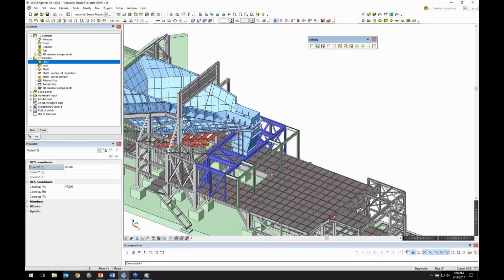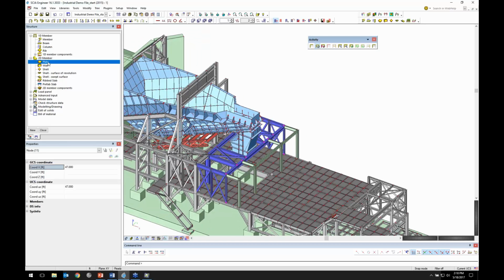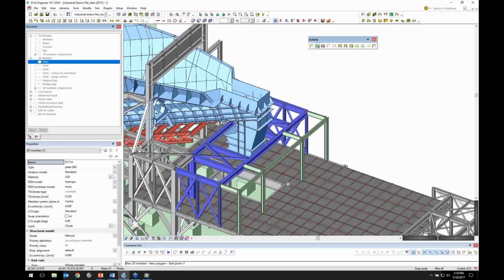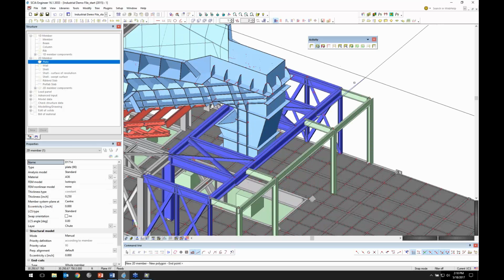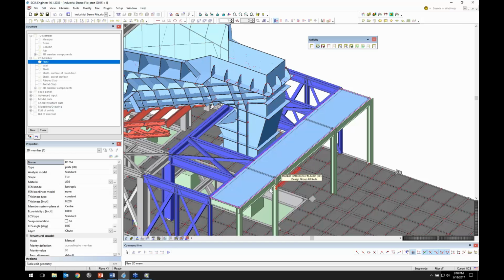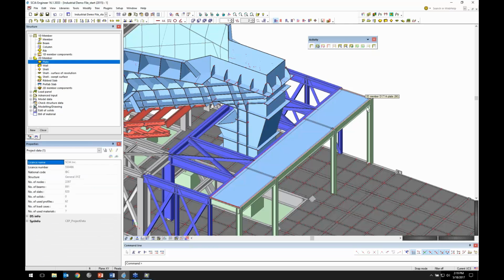Now in addition, we can go ahead and add in a steel plate on the floor. So again, we can maybe choose a certain thickness and just use our snaps to model in the extents of a plate. So I'll just drop a plate on this particular portion here. And so we could put a plate on that. That can be a deck. We could change that to a metal deck of some sort and then choose a Vulcraft metal deck or something like that. It's completely up to you at that point, and it's really just a matter of how you want to model.